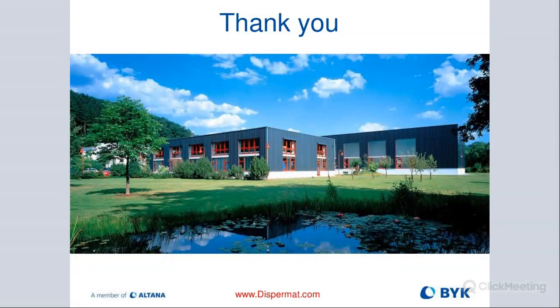Appreciate it. Thank you. A couple questions here. This was towards the beginning of the presentation. Brittany comments, viscosity at what shear rate? That really depends on the product, so I'm not sure I can give you a correct answer. Usually we're talking 3 to 10,000 centipoise, so regular flowing material, like regular paint. But it's application specific, yes.